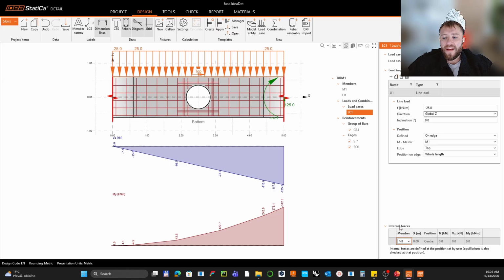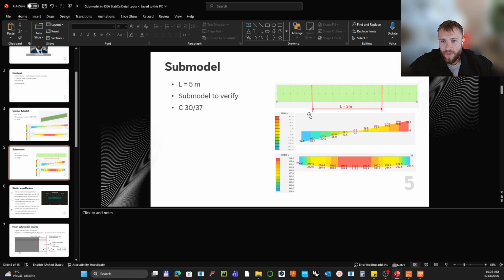Right now, as I know that the support is basically here, I'm able to modify the section of my diagram. What I need to have at the end of the trimmed end is 62.5 kilonewton, and the bending moment at the trimmed end 234, in the middle 312. So I can take advantage to assign the bending moments and the shear force directly to the section in the middle, because you're able to utilize every section wherever you want.